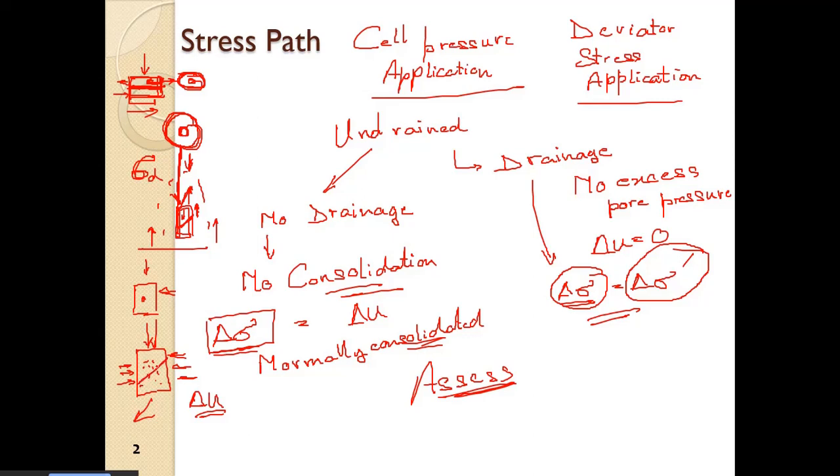So ultimately, what are the differences? How do the stresses change from one condition to the other, and at what condition of stress, what configuration of stresses, the sigma C, sigma D, at what configuration of U, does the soil ultimately fail? So we need to assess that. So to understand or to comprehend that particular aspect, we have developed what is called the stress path.